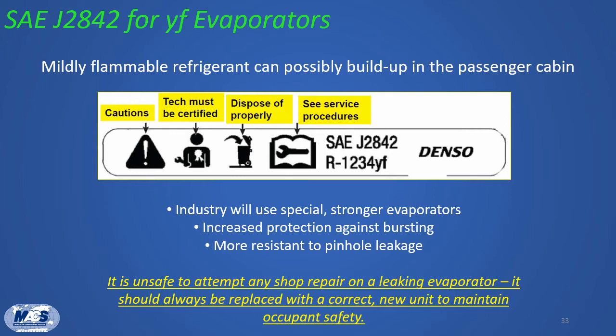Because R1234YF is a mildly flammable refrigerant, there is a concern that if an evaporator were to develop a leak, refrigerant could possibly build up in the passenger cabin. Although manufacturers take precautions with system design, industry will use special, stronger evaporators with increased protection against bursting and that are more resistant to pinhole leakage.